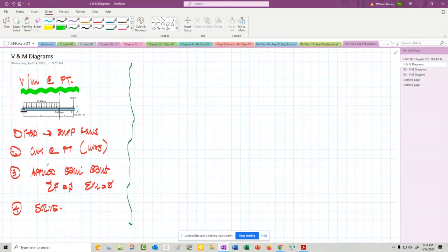So we want to find what the maximum we expect is, and then during design, they'll actually add a factor of safety on top of that, just to be extra sure. It's kind of like an elevator. They can design it to hold 10 people, because they figure that's the max number of people going to be in there, but they know that people aren't counting as they get in the elevator, so they're going to design it for a few more than 10, knowing that it possibly could go that high.